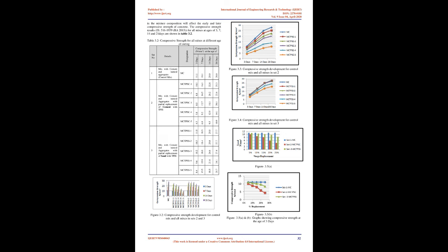The results indicate that the use of TPIS led to a decrease in the density of the concrete mixes as compared with the control mix. This is because of the lower specific gravity of the TPIS as compared with cement and sand. The mixes with cement and natural aggregates with partial replacement of cement with TPIS indicated lower densities relative to mixes with partial replacement of sand with TPIS.